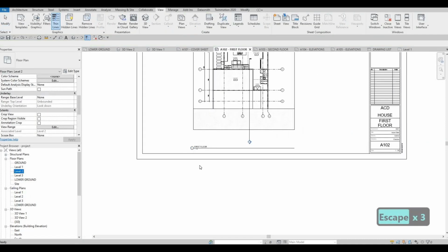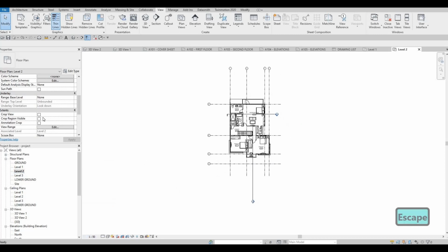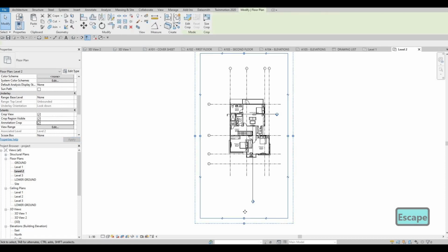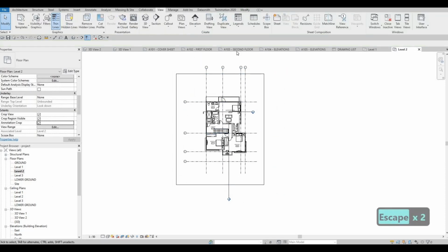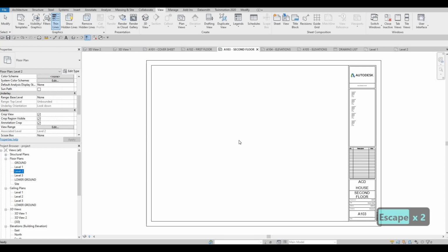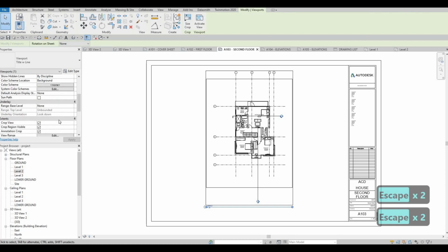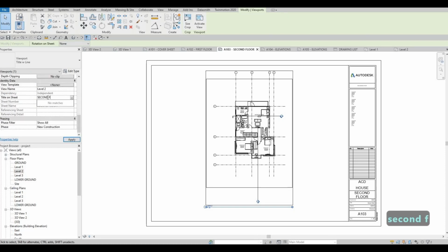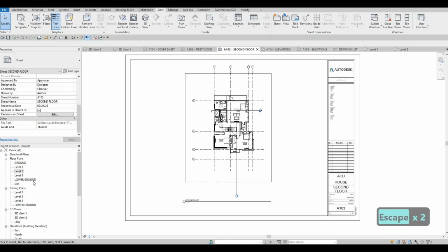After that, because we know everything that we need to do right here, so change to 1:50, check all of this, click apply, fix right there, and we just need to go to second floor, click right here, add it in the middle, select this one, and change this to second floor. Click here and then click apply. So now everything is similar.